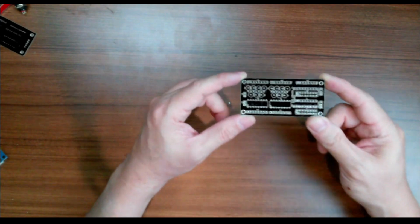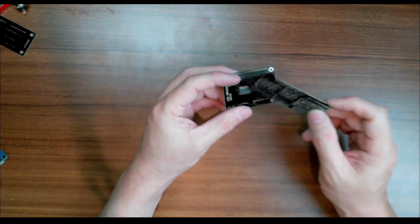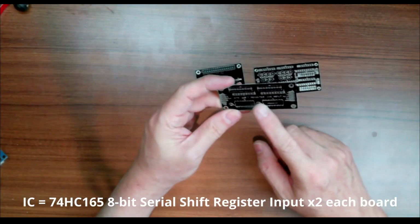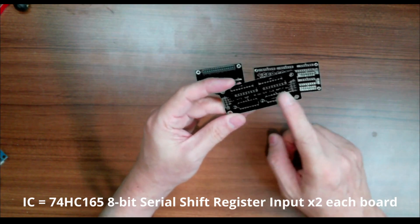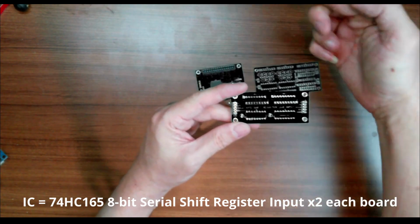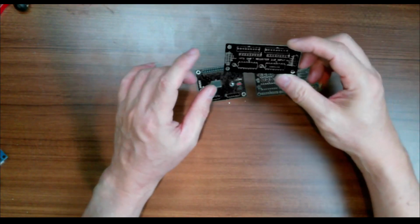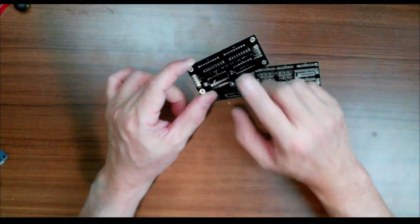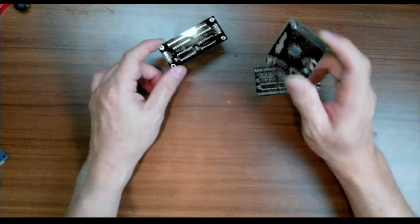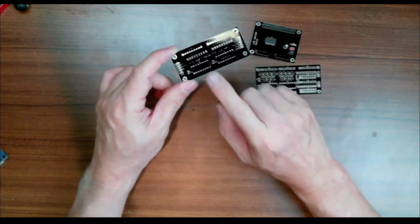without a serial shift register, because you can use a shift register here, or for the input you can also use a shift register, specifically a 16 bits shift register for input. So the switch will go here, and then it will shift back into the Arduino 2560. So you can save a lot of pins by using shift registers. I think we can drive 3 boards like this, a shift register, you know what I'm saying, and 3 boards like this.